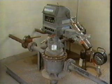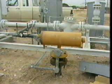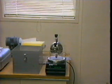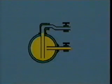Just as volume measuring meters must be proved and calibrated, the densitometer also must be proved. To prove densitometer accuracy, a pycnometer is used. A pycnometer is a high-pressure vessel of certified volume and empty weight. NGLs flow into the pycnometer. A volume is captured and then weighed. Density is found by dividing the net weight of the NGLs by the known volume of the pycnometer.